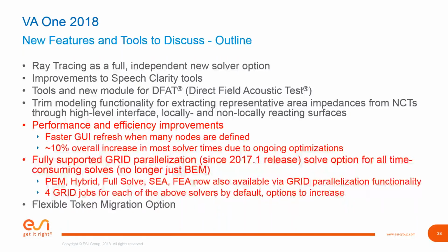This isn't an add-on. If you have enough licenses to run this, then it's simply available. You can piggyback and use grid parallelization for things that take a longer time. You break it into different grid jobs. Those are batches of frequencies. So for example, you might break things into 4 batches of frequencies, each solves independently, and the grid tool will merge the results at the end.